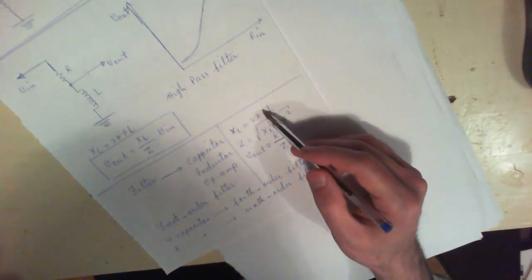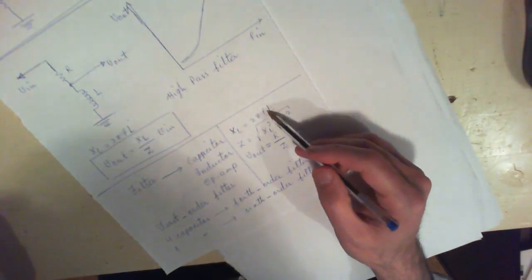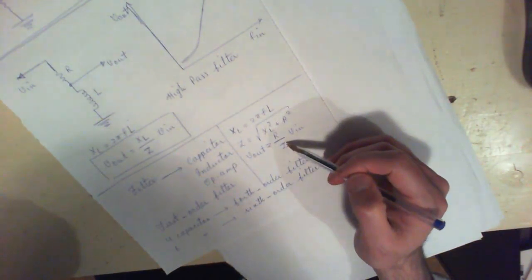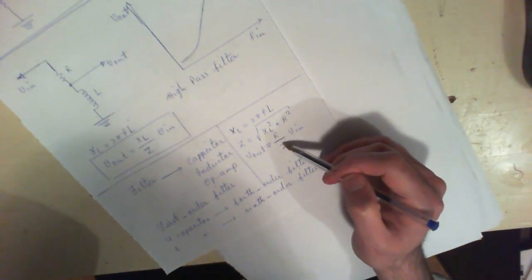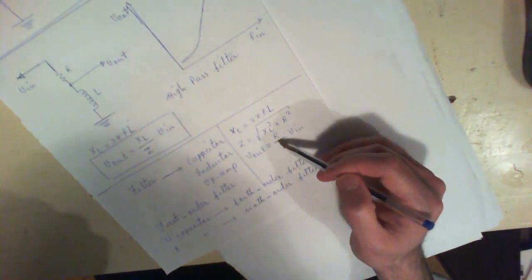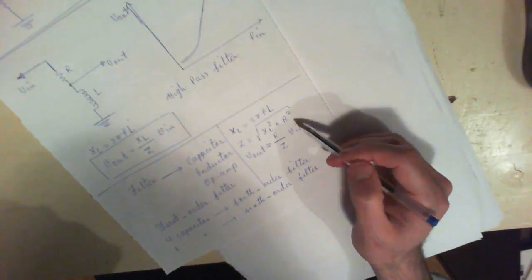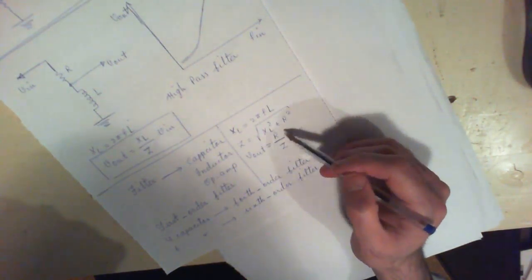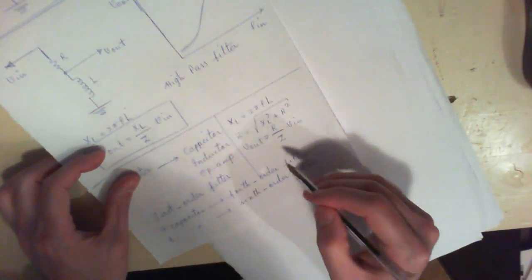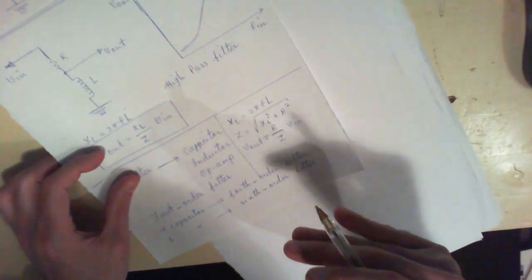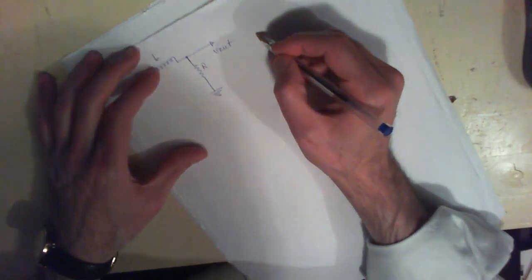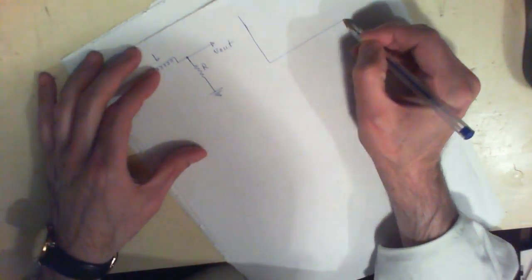With that your impedance increases, the value of this fraction gets smaller and smaller, and you are having smaller and smaller fractions of your input voltage at your output. So as you increase your frequency, your output is going to get smaller and smaller, and that's what happens in the case of this circuit.